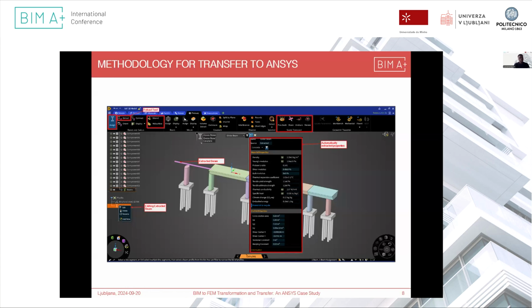This also helps repair geometry if there are any gaps, because when you extract a profile from a solid geometry, it creates an analytical line at the neutral axis of the model, and this might cause gaps within the analytical model.